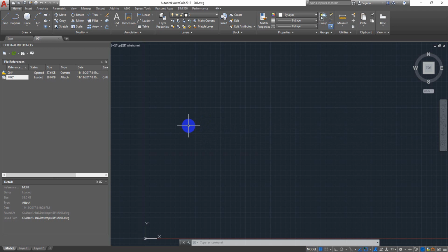Now what is the real life example for this? You can think of a drawing grid as an xref file which is saved somewhere. When you have a floor plan, you xref the grid first to the blank drawing. Then, based on the grid locations, you draw your walls. That is the best practice I would suggest.